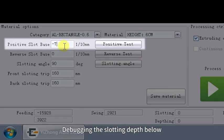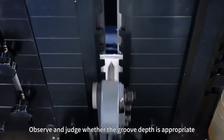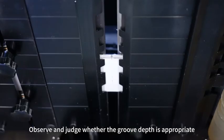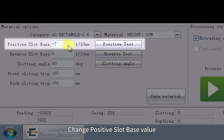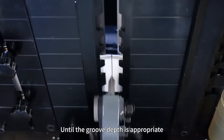Debugging the slotting depth below. Click Positive Test. Observe and judge whether the groove depth is appropriate. If not appropriate, change positive slot base value. The larger the value, the deeper the slot.